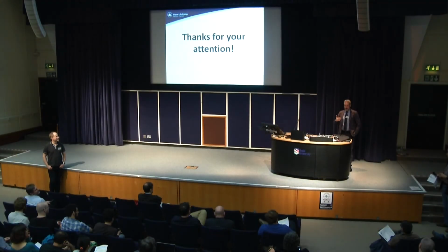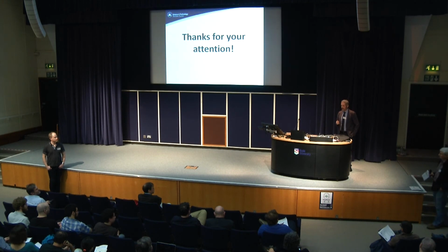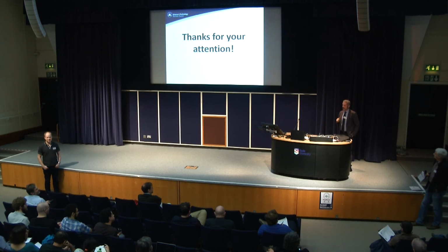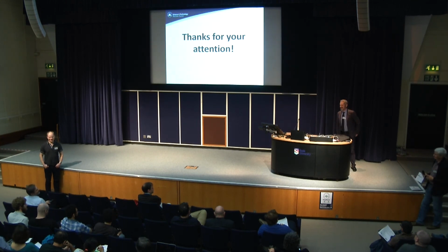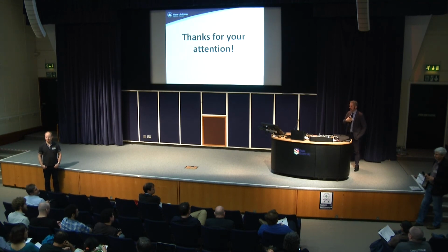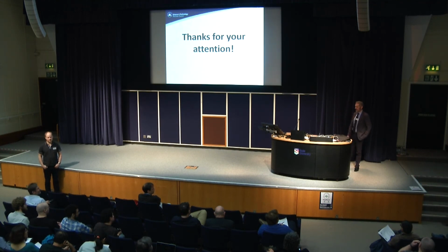Does your detector give us that raw image, or do you do some processing to it before? This is another bone of contention, because in order to reduce the data rate, we suggested several times, can we do some processing on the ASIC, because that will reduce the amount of data that has to be handled. But the scientists are very reluctant to see any processed data. Even if you correct for some dead columns, they want to see the dead columns. So it becomes a bit of a challenge for us. From a certain point of view, for us it's simpler. We just provide the raw image. But yeah, that is part of the conversation that I was mentioning before. Okay, thanks.